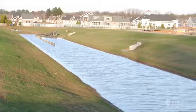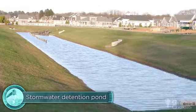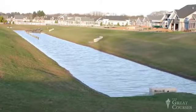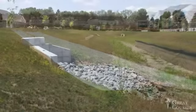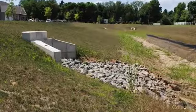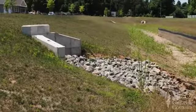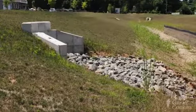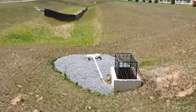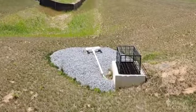Well, the answer is to incorporate a stormwater detention pond into the site design. A detention pond is an earthen enclosure, typically located near the outlet of the development's storm drainage system. Storm drains discharge into the basin at outlet structures like this one. The basin stores the runoff temporarily, allowing some of the water to infiltrate into the soil and some to evaporate. Peak runoff from large storms is released at a controlled rate from an outlet structure like this one into a local watercourse or an existing storm sewer line.